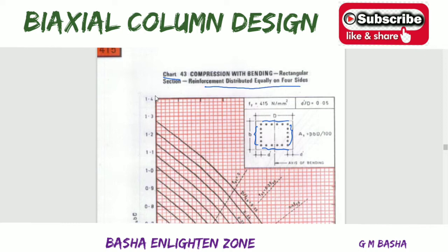But yesterday I showed you the model also like this, reinforcement distributed equally on two sides only. So there will be such types of graphs. So before going to solve a model, you please choose the condition, assume any graph according to our condition, whether you want reinforcement equally on all four sides or reinforcement equally on opposite faces, that is your first condition. So here I am choosing equally on 4 sides.